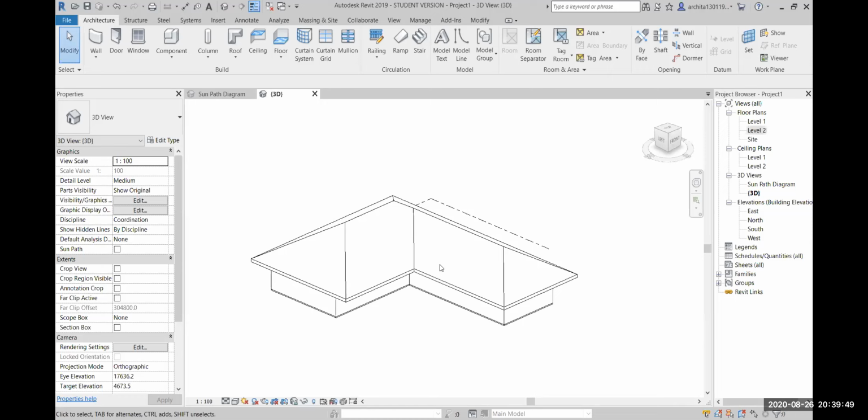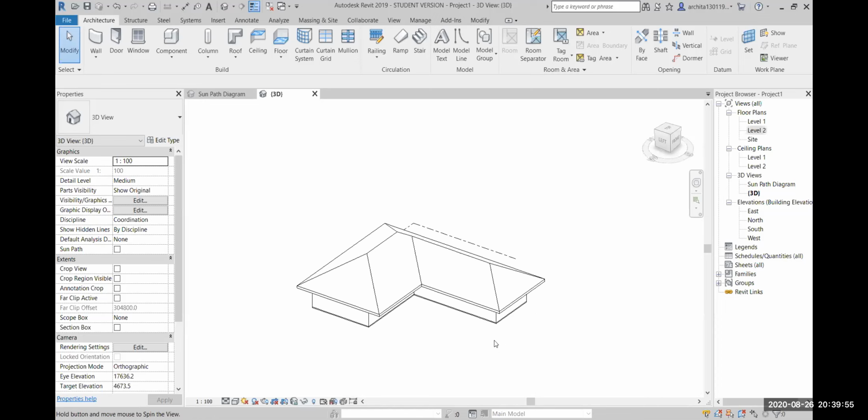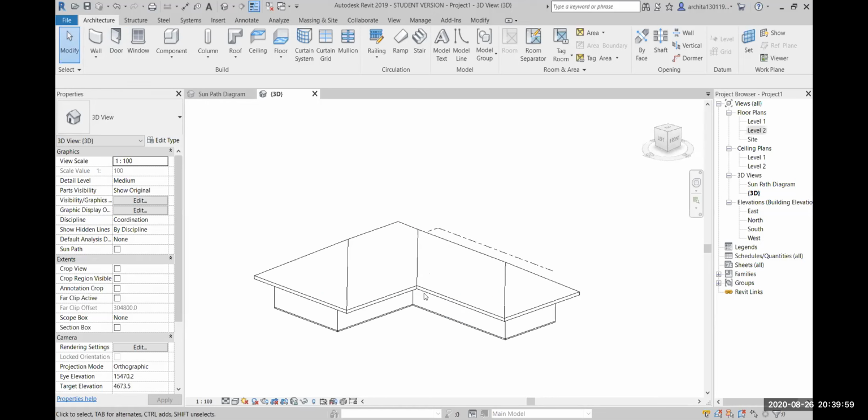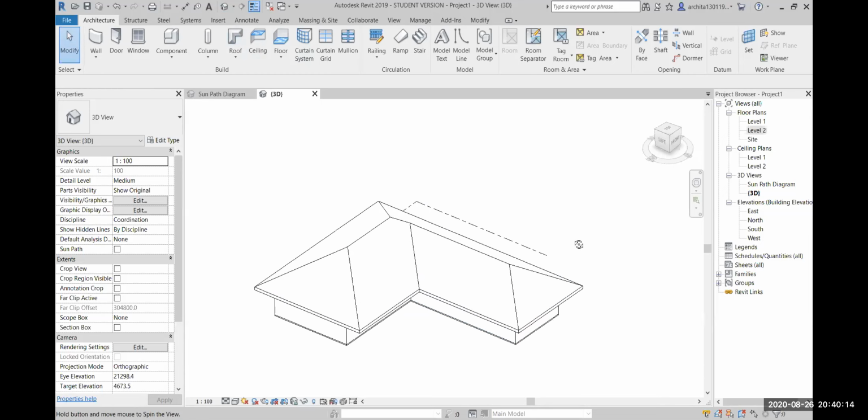Okay, ma'am. Okay. Yeah. So now after this part, like you know how to create, how to freeze this entire view. Now we will learn another important thing, which is exploded view. We can also create exploded view. How to do that? Now go to your default view, okay? Default 3D view.